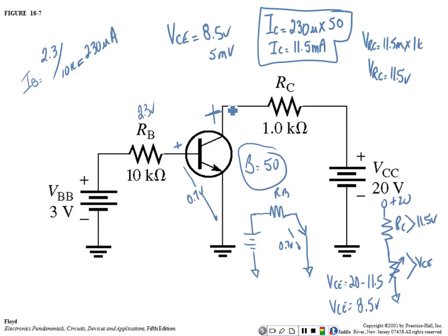And we treat this like 2 series circuits, which is pretty neat. The series circuit on the left is controlling the series circuit on the right. So what is gain? Gain is out divided by in. That's all it is. How much you get out by what you put in. That's gain. Right? You understand? And that's what beta is. Beta is the current gain with the emitter common. That's all it is. HFE.